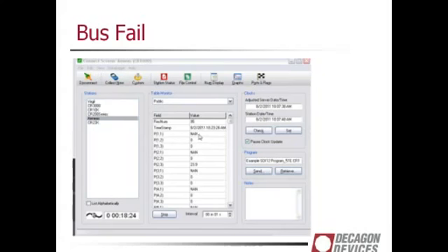Notice here that this would be where your water content numbers are. It's not coming up as anything, but you are getting data. So there's a sensor here that is getting a signal through. It's hard to tell exactly what the problem is with this bus, whether it's not getting power, but notice a temperature reading is coming through here, so you can get some very odd readings. It looks like it's almost working, and I tested all these sensors later, put them on a good bus, and they all ran fine. So putting a good bus out in the beginning is important, but also being able to test it and test your sensors individually is also very important.